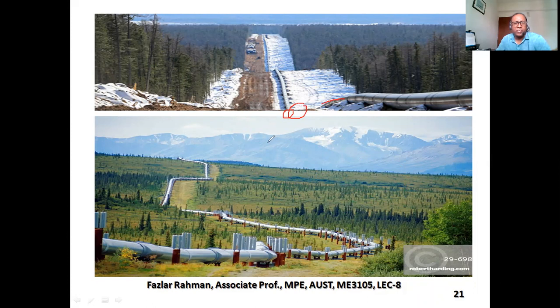For example, through a pipeline, water is coming. So at this point, you apply Bernoulli's equation. You get P by gamma, you get V squared by 2g, and you get Z. Say P by gamma is coming, I'm saying 70, V squared by 2g you got 20, Z you got 10.